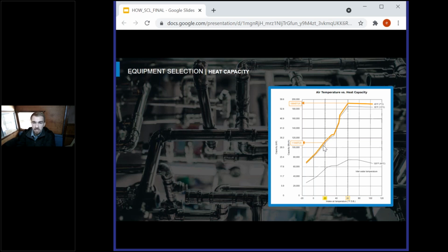And then another thing you need to think about is these air source heat pumps, they accumulate ice on their coils, so those will freeze up and require a defrost. So there's going to be a specific defrost rate depending on the heat pump you choose that you need to get from the manufacturer, because if it's rated at 110,000 BTUs, that's likely not including the defrost cycle. So over the course of an hour, it might not be that 110, it might be, say, 80,000 BTUs. So that's the number you want to look for when you're designing for the worst case scenario in these systems.